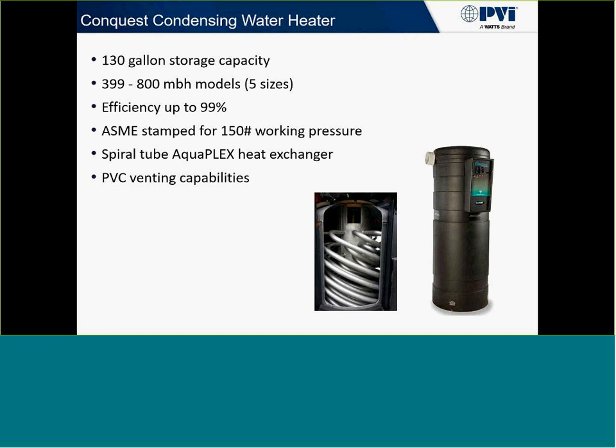But because they have to push so much air and heat through those heat exchangers, they have to have a very large blower to accommodate that. With this being a single pass design, our blower doesn't have to be nearly as large, which means it's a lot quieter. So for hotel situations where the acoustics might be a detriment to the aesthetics for hotel owners, that's a very important attribute that a single pass design has versus a multi-pass design heat exchanger.